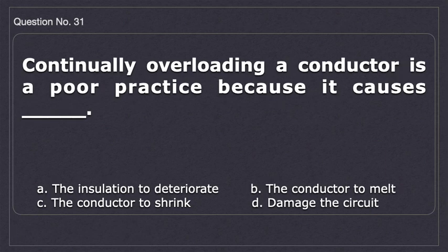Question number 31. Continually overloading a conductor is a poor practice because it causes blank. A. The insulation to deteriorate. B. The conductor to melt. C. The conductor to shrink. D. Damage the circuit. Answer, A. The insulation to deteriorate.